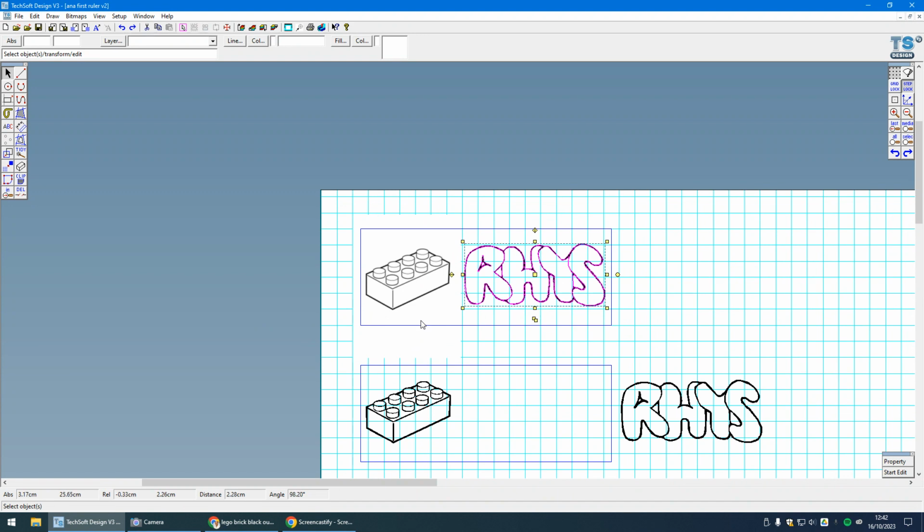Now let's have a look at the image here. I have to say with this image, I've purposefully gone with an image for which there is a big margin around the outside, which I would suggest we avoid. I've found it's a bit random. On some occasions it causes a problem with the laser cutter, and the laser cutter thinks that the actual graphic I'm laser cutting is right out here, and at other times it ignores the margin and just cleans the CAD file up.